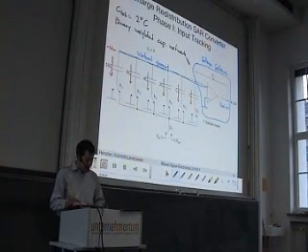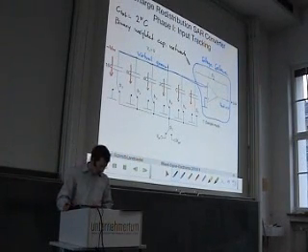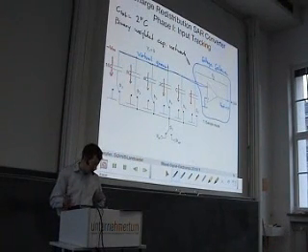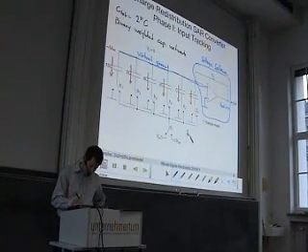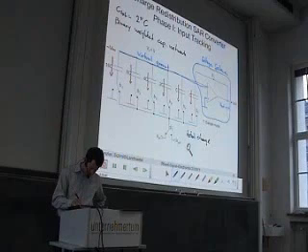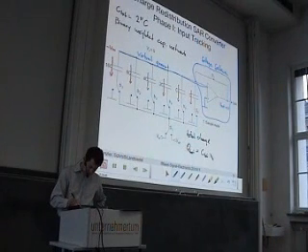And of course, if we have a total capacitance, we have a voltage drop across all caps that is known, then we can also compute the total charge. And this total charge is Q total equal to C total times the voltage, which is minus V in.